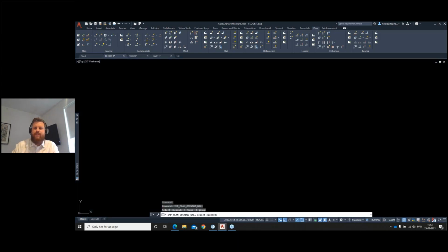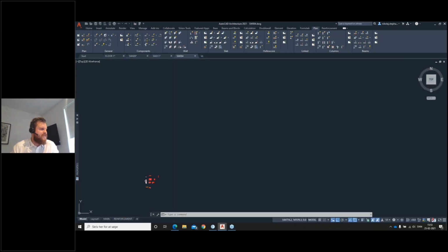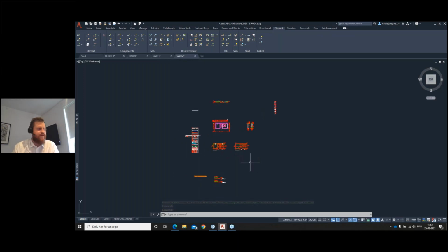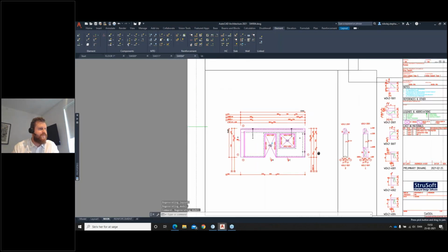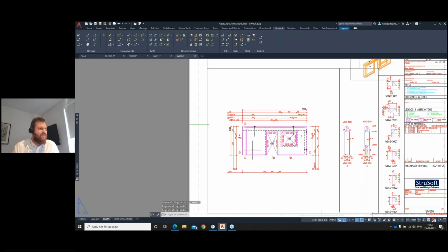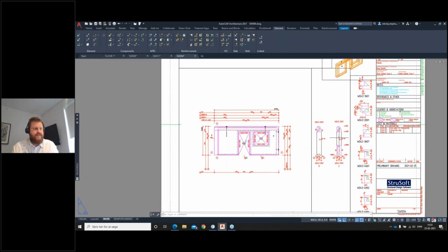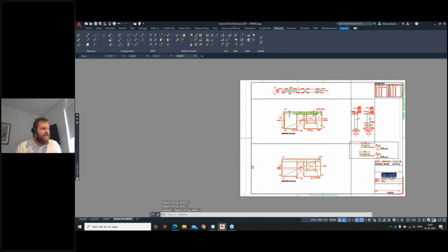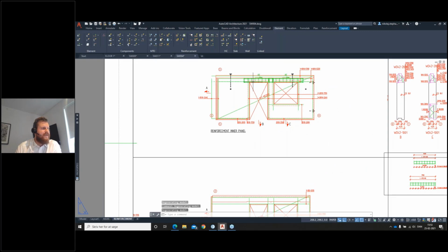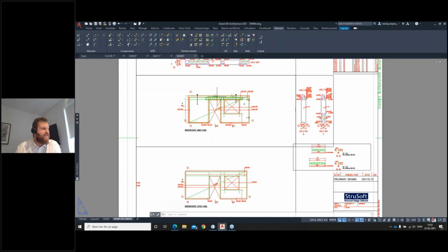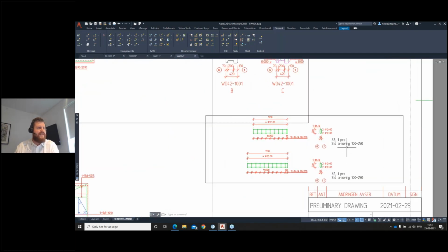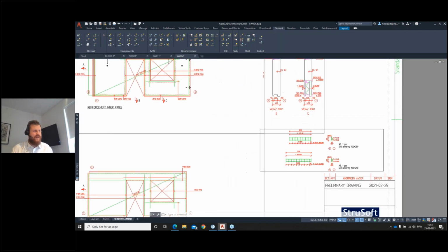And basically, while we're working through the model, we are filling into the system the information that we actually need to create these things. So here you can see, here are more things than on the others. If I go into main, it looks the same, but it scaled the drawing down a little bit to fit these 2 sections. It automatically created a section in the door and automatically created a section in the window as well. Furthermore, the door and the window in this case have automatic reinforcement in them. So that means that the reinforcement is automatically put in as A3 and A5, the placement, and here as well, the details of how to actually make the A3 and the A5.